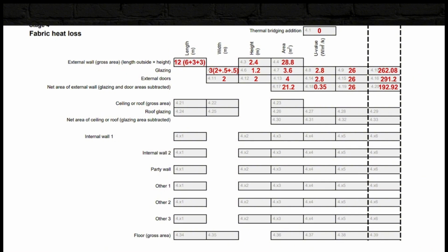Now, the interesting thing is the area of our outside walls is over 20 square metres compared to our French doors, which are 4 metres, so 5 times the area, and yet the energy loss is lower. It's all about insulation and efficiency. Windows are much less efficient at withstanding that thermal movement than our insulated walls with our high performance block.